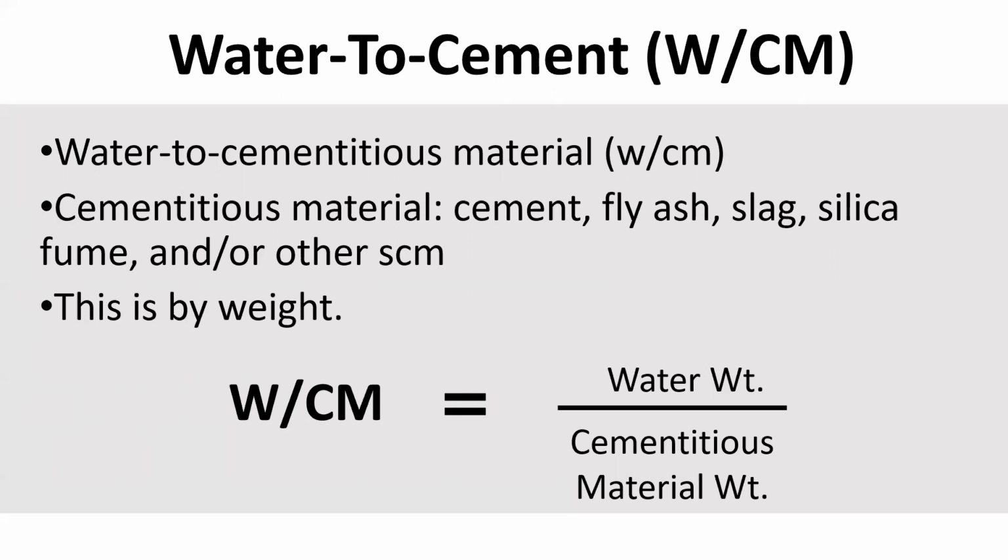The more water you add, the more you're diluting your cement, so it has less and less impact. You're going to have lower strengths normally, it's going to change your setting time, and you could even have cracking issues because the concrete's not going to have those good internal stresses.